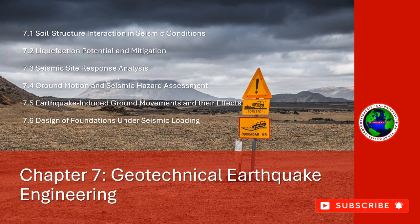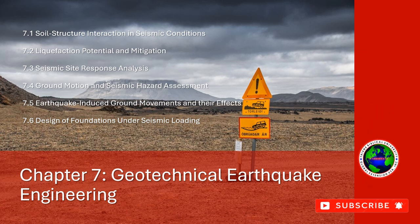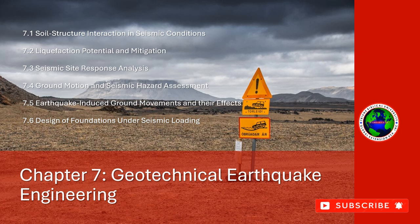Seismic site response analysis helps to evaluate the potential for liquefaction at a site by modeling the intensity and duration of shaking. Strong ground motion from site response analysis can be used to assess whether liquefaction is likely to occur in specific soil layers, particularly in loose, saturated sands.